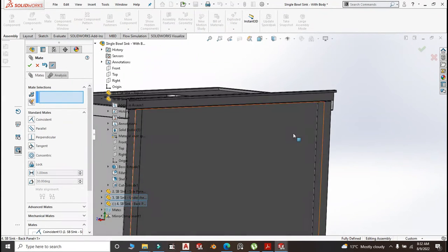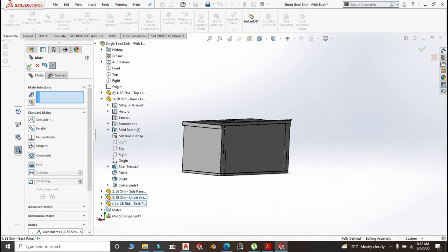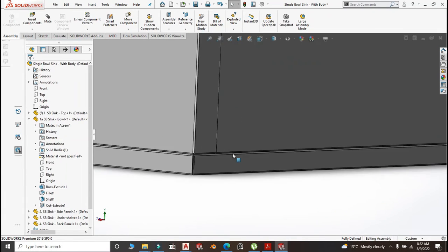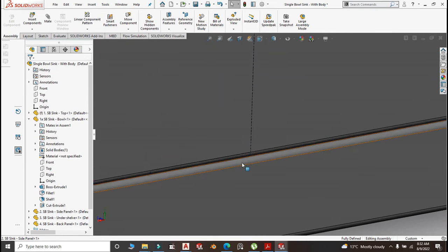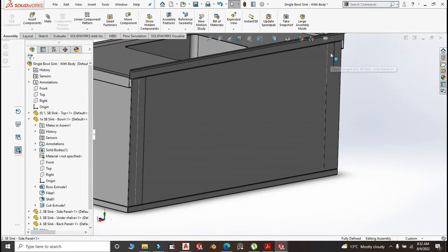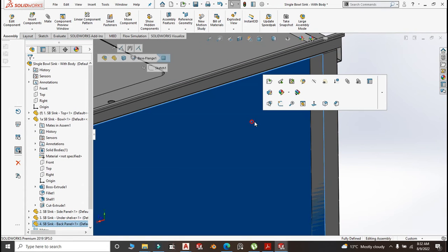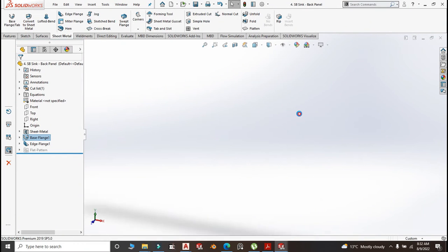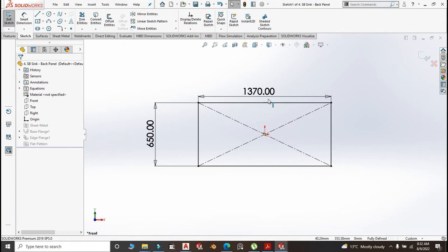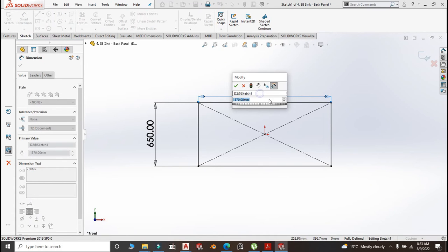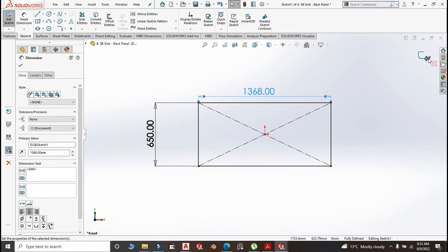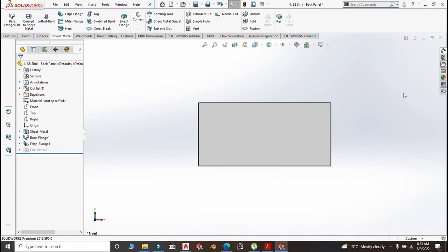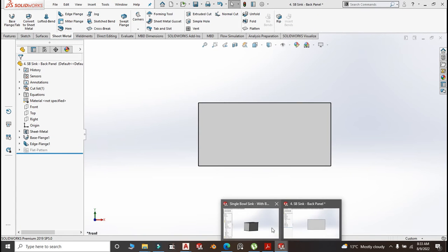Now you see where your joint will be. I hope we should have given it a 1 millimeter, 2 millimeter allowance so that they may not overlap. So we could have edited it from there, but now that we are here, minus 2 millimeter, 1 millimeter from each side. Yes, we don't want it to be tight. It will start bulging.